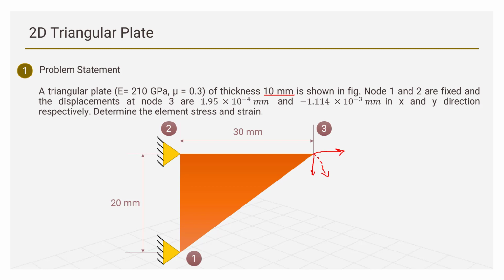In FEA we first solve and get the primary variable, that is U. Now this primary variable varies linearly throughout the element, so its dependent secondary variables, or its derivatives such as strain and stress, are constant. Therefore, as strain is constant throughout the element, it is known as a constant strain triangle element.